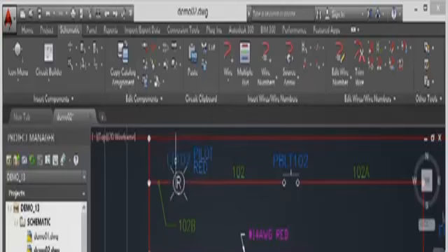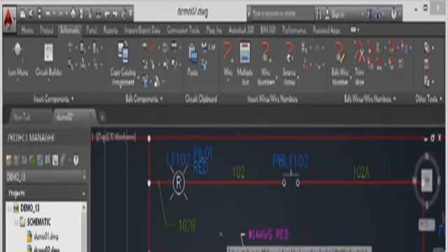Now, you'll notice that with LT102 and LT105 that we've used in the previous videos, there is an R in the center there, indicating that that is a red pilot light. So up here for LT102, that red attribute doesn't actually need to be displayed. So I can select the component, right click, and on the shortcut menu, I go to Attributes here, and I go Hide Attribute.